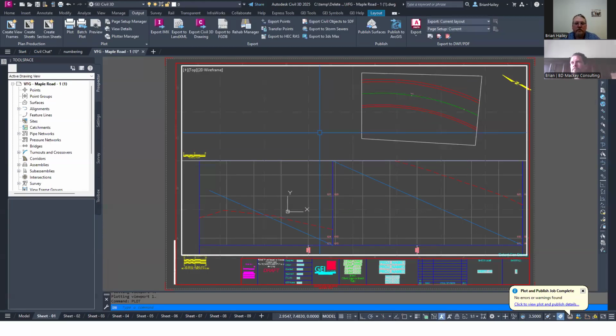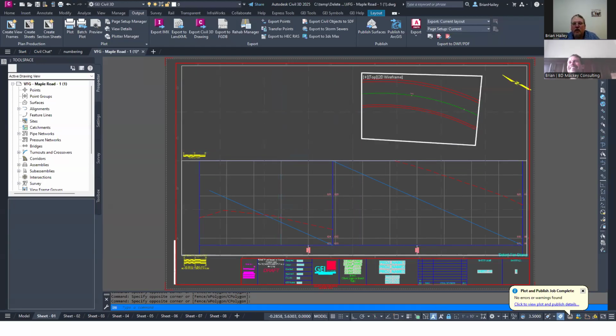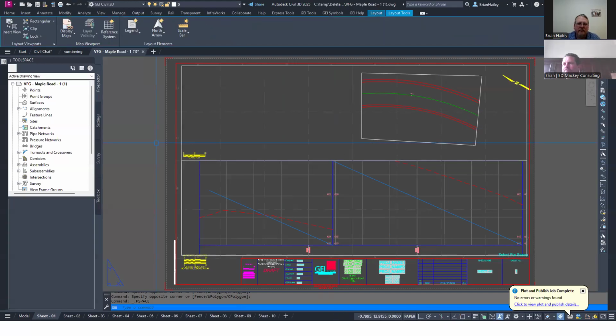But yeah. So here's an interesting one. This particular template, unbeknownst to me, and I'm going to have to go fix this now, actually had a viewport that went all the way around both of these other viewports. And I'm currently in this viewport. How do I switch over to one of these other viewports? Did anybody ever find themselves in this situation? You delete the large viewport you don't need. Right, but let's pretend I did need it. All right, so Control R will cycle you through all of your viewports. So I'm just holding down the Control key and then tapping R. That'll cycle you through your viewports. That's just a nice little tip to have if you ever find yourself needing it.